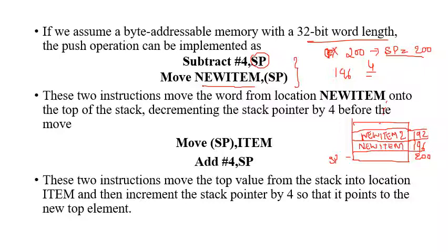here what you need to do is, initially see this particular stack grows in the lower order address. It starts from the highest address and it keeps on decrementing until the starting address of the stack, or there is a range, as I said earlier, until the last address is reached. So here, when you retrieve, the stack pointer will be pointing to the current address. So that is the current address in this case is again 192.